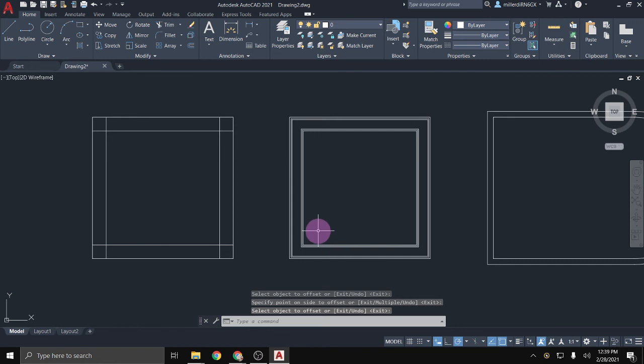And then if I go back into offset, O, enter, now in those triangular brackets, it says 3. So that means that's the very last option I chose. And AutoCAD is assuming, unless I tell it otherwise, that that's what I want to do again. So unless I tell it no, I want to do through this time, so I'll do T, enter.